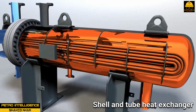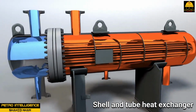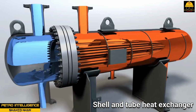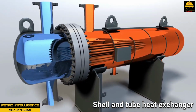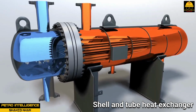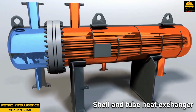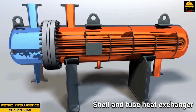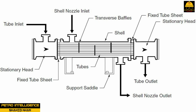As the tube side flow enters the exchanger or head, flow is directed into tubes that run parallel to each other. These tubes run through a shell that has a fluid passing through it. Heat energy is transferred through the tube wall into the cooler fluid. Heat transfer occurs primarily through conduction first, and convection second. This picture shows a fixed head, single-pass heat exchanger.